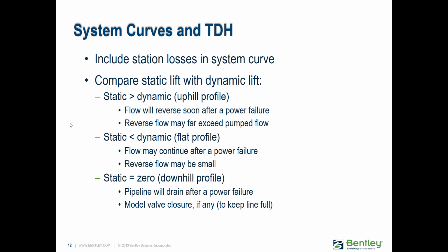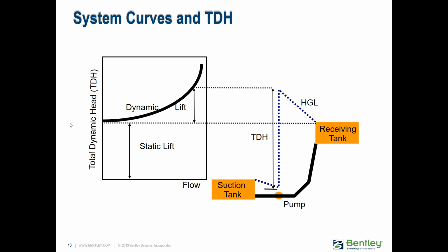So there's two components to the system head curve and the head that the pump is adding, and that's actually defined in this next slide here. You can see visually, this dark black curved line on the left side is your total dynamic head.